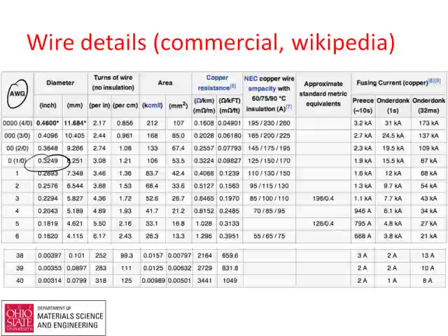Well, you look at resistance. You can look at the resistance of this thing in terms of ohms per 1,000 feet. It's a very small fraction of an ohm per 1,000 feet for a wire like that. And with a big thick wire like that you can carry 125 amps and keep your insulation very cool. You can carry thousands of amps with it before it vaporizes. That's the fusing current. And that's for really big wire, what you'd see for powering buildings and such. But much more interesting for the classroom is stuff you can buy very cheaply down here.